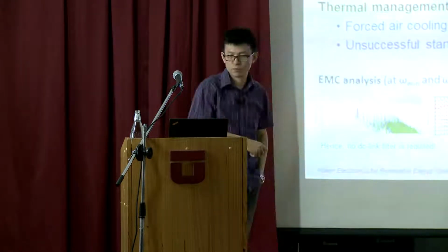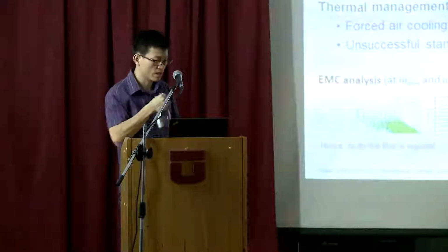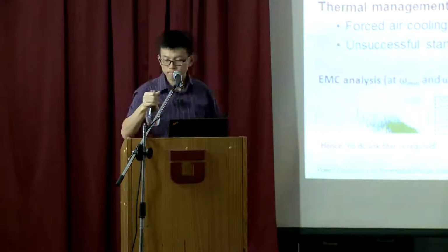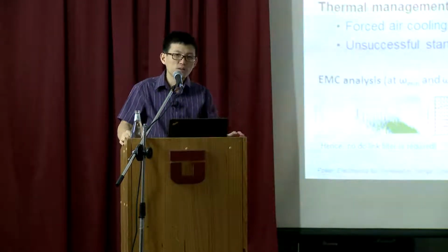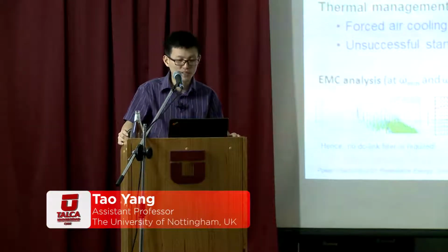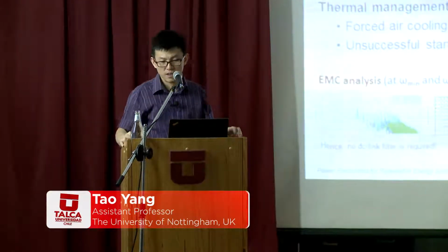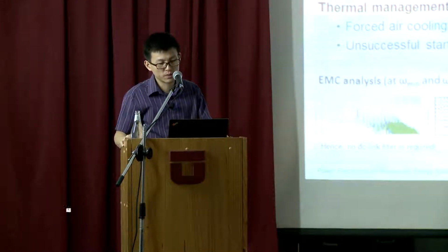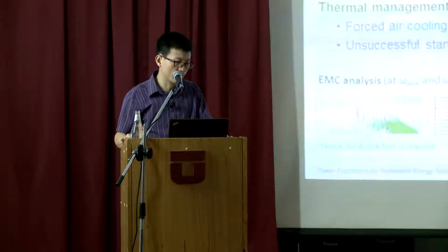So this is the converter, very briefly. I think yesterday one student asked me what converter we're using. For aerospace application, we make it simple: either 2-level or 3-level at the minute. The DC link on this side, at the time when we did this project, was 270 volts, and now we're looking at 540 volts.